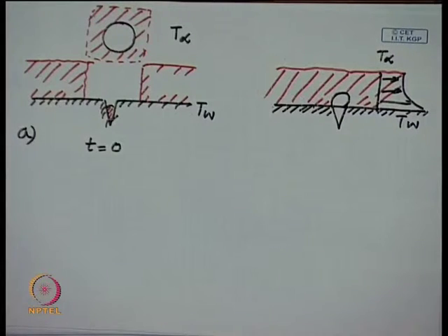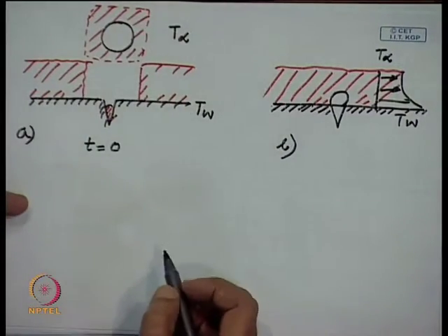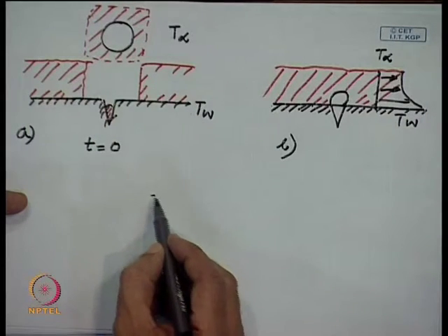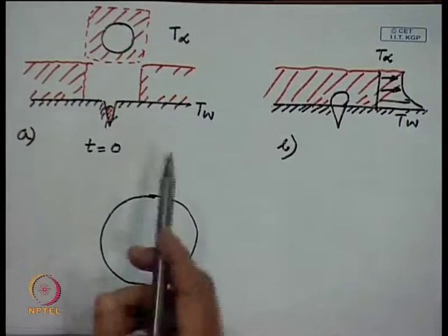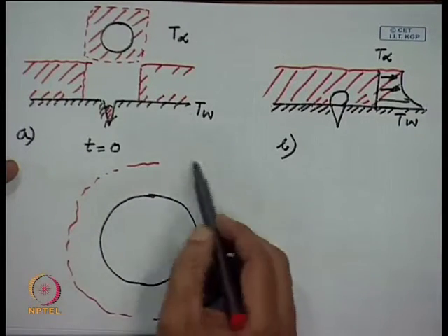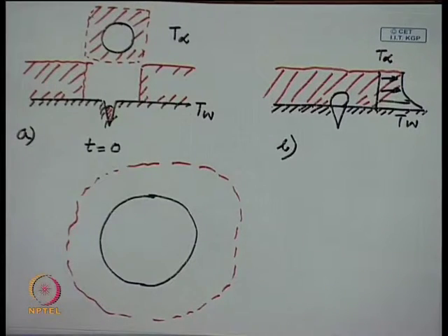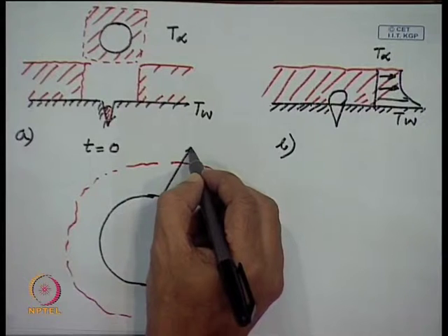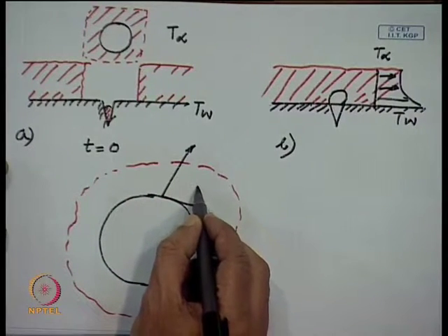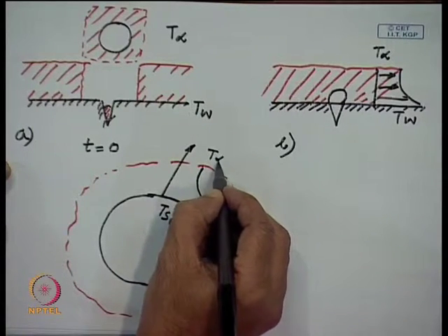So, this is very important. At this point we come back again and again to the fact that the superheat is very important. Let us modify this diagram slightly. Say this has created some sort of jagged liquid layer over the bubble, not exactly rectangular as I have drawn, but some shape like this. Suppose I want to know how the temperature varies along this radial line. It will be something like this. This is your T sat, this is your T infinity.